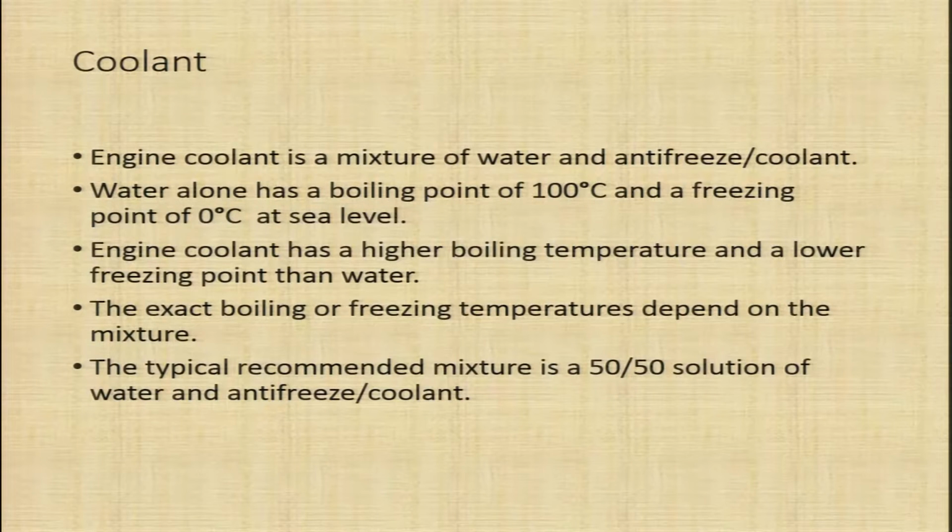Water alone has a boiling point of 100 degrees centigrade and a freezing point of 0 degree centigrade at sea level. Engine coolant has a higher boiling temperature and a lower freezing point than water. So, the advantage of engine coolant is that it has a higher boiling temperature and a lower freezing temperature as compared to water. The exact boiling or freezing temperature depends on the mixture. The typical recommended mixture is a 50-50 solution of 50% water and 50% antifreeze coolant.